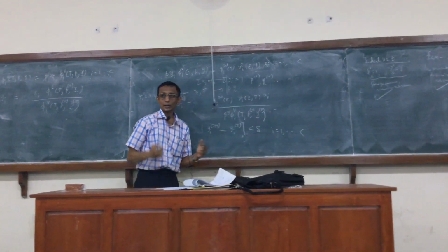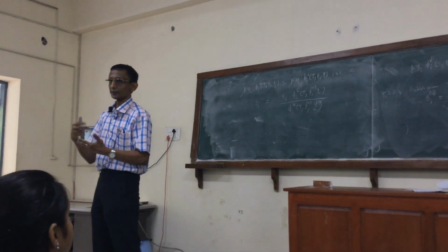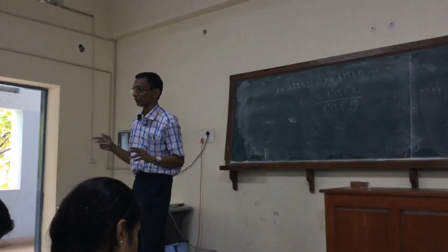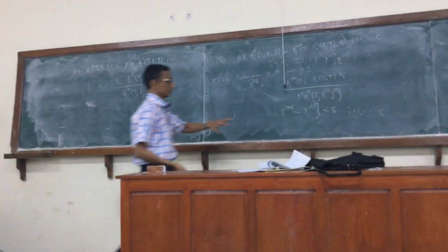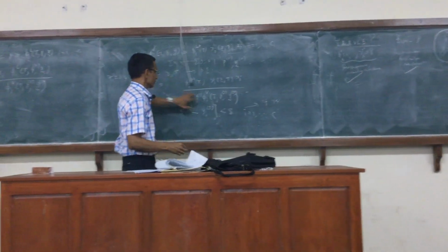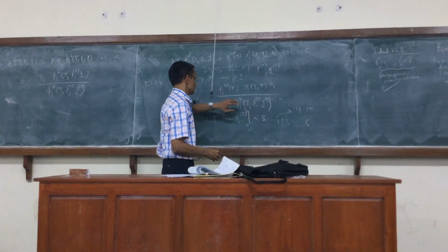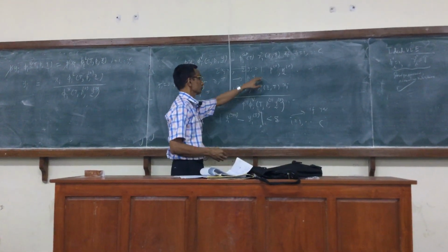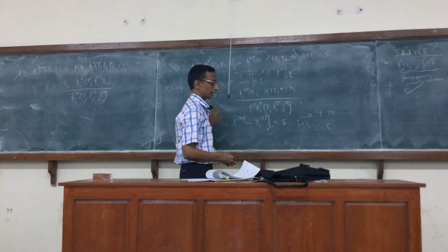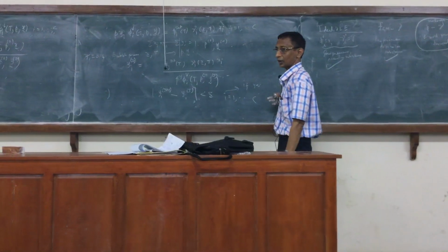The first thing I would check is that difference. Because the inner loop will check only the difference between successive mole fractions of the iteration. We don't check the mole fraction constraint at any point. And it is continuous. If no, then we go back. So if we start with P naught, y naught, then I will simply put P1, y1 here and then y2. So if we have reached this, then the next part of the algorithm is updating the pressure.